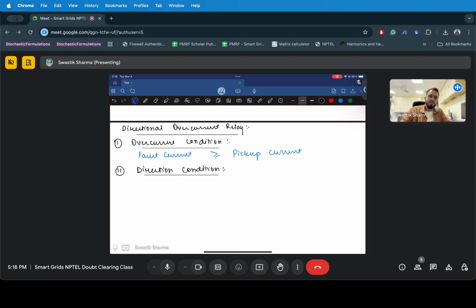It's because you want to make sure that the kind of fault current you're witnessing is appropriately handled, so that you issue a trip signal to the relay without disrupting the flow of current to different feeder sections of the feeders, right? And that's where the direction component comes into play, because there is bidirectional power flow in smart networks now, smart distribution networks.